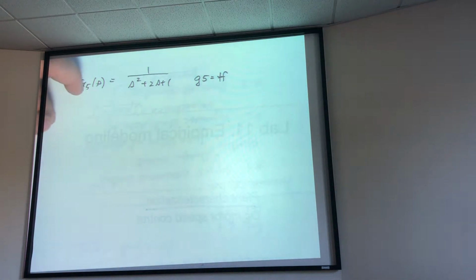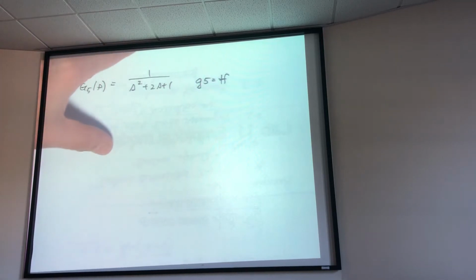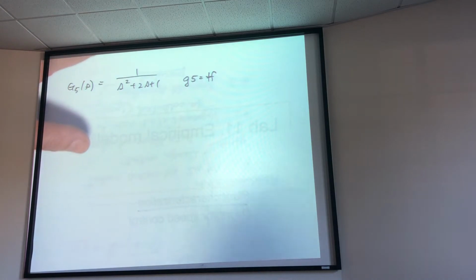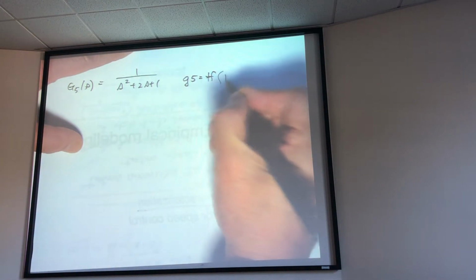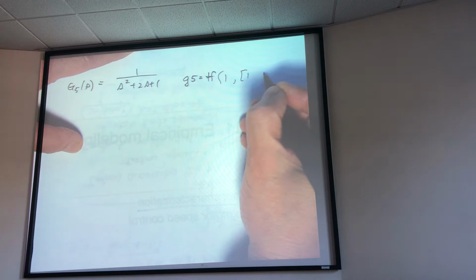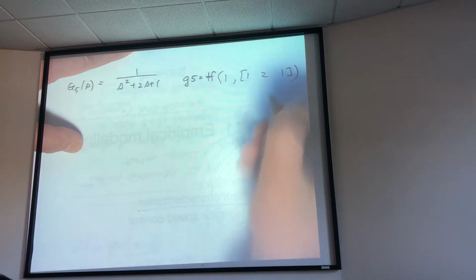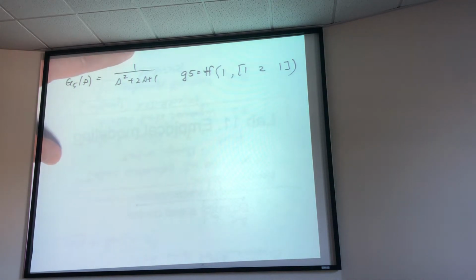A pure LC circuit would be an oscillator. It has no damping. It would have complex poles. This one has real poles, so it's an RLC circuit. The numerator is 1. The denominator is s squared plus 2s plus 1, like so. Let's do root locus.